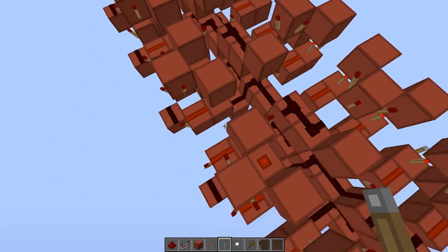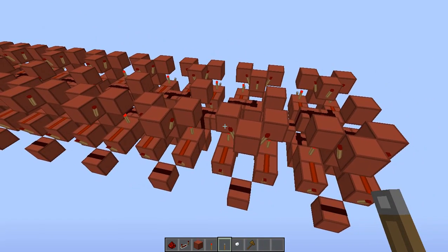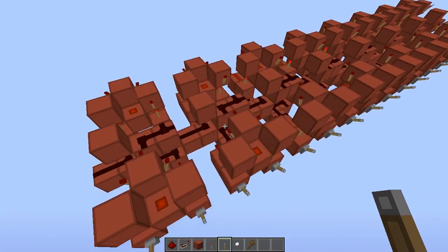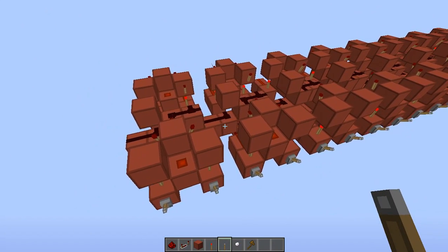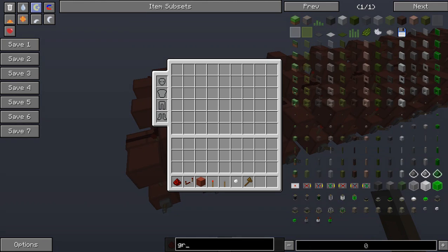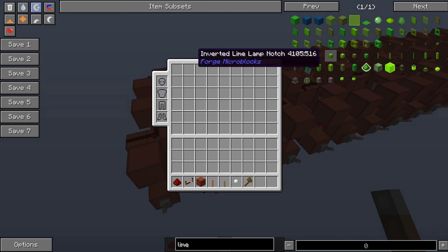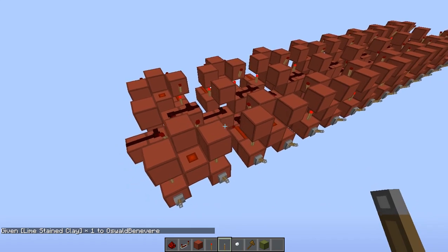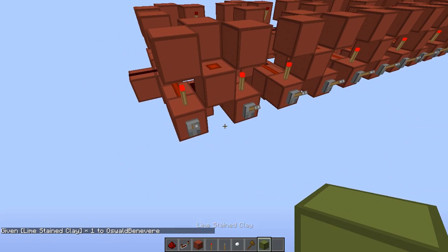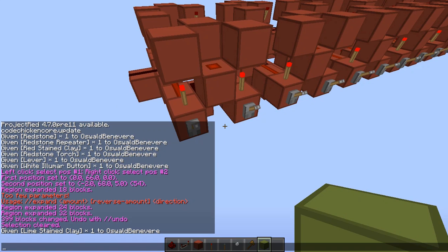So now, this is all addition, but what if we want subtraction as well? Well, fret not, because it's actually pretty simple. We're going to go grab some green clay, because actually, you know what? Lime will look better. Yeah, there we go. The way we do subtraction is to do A minus B, that's actually the same as doing NOT of (NOT A plus B).